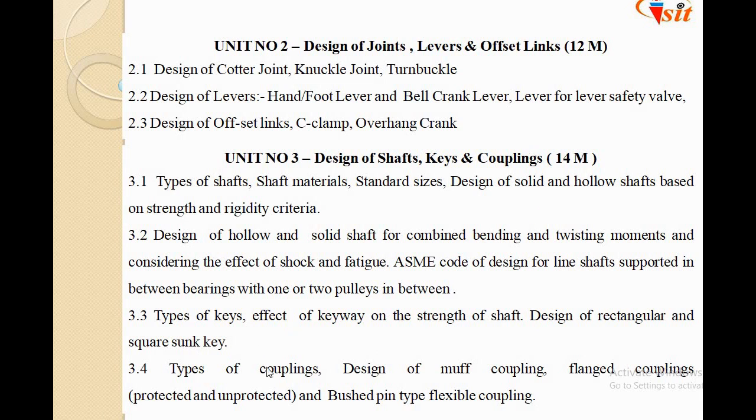Now the next part is the types of couplings. To couple means to join. When we have to transmit the power for a longer distance, then we have to join two or more shafts to each other. That task is carried out by using different couplings. For our unit, it is restricted to muff coupling, flange coupling and bush pin type flexible coupling. So we have to design muff coupling, flange coupling and bush pin type flexible coupling. This is regarding topic number 3.